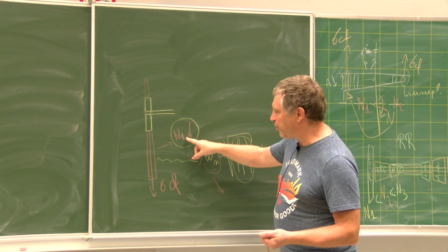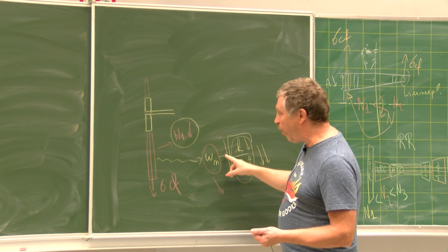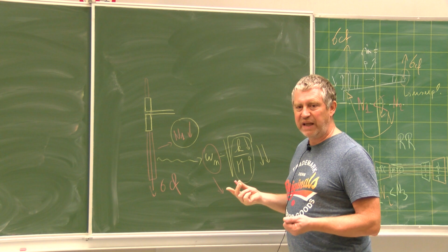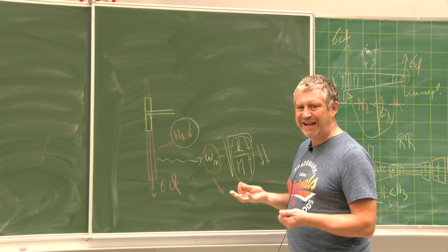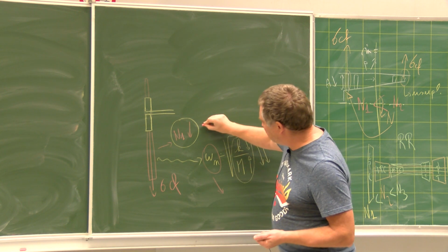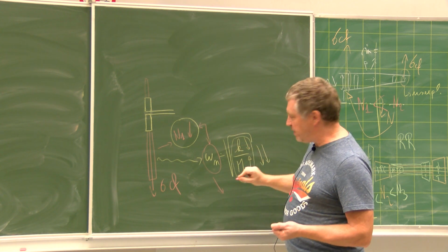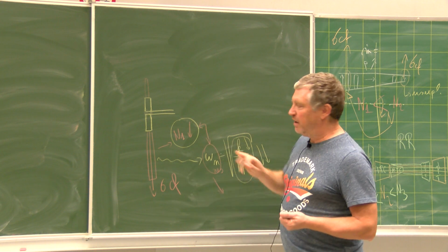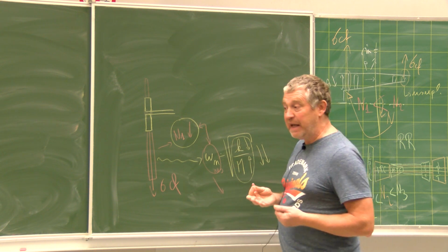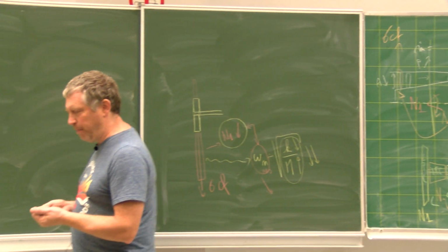And so when you are increasing the rotational speed, you need to go over this value, and you could have resonance when you are accelerating the engine. And so the combination of a low resonance frequency and a low rotational speed can become a huge problem.